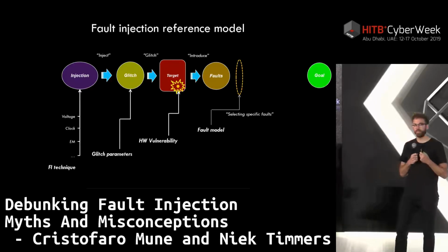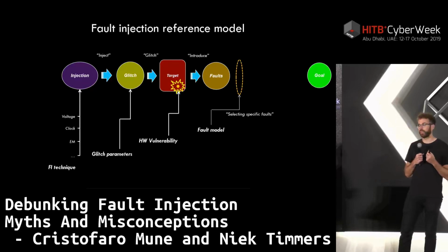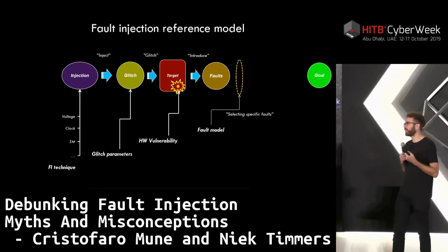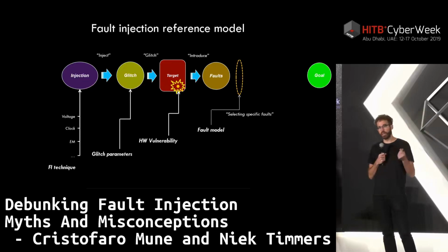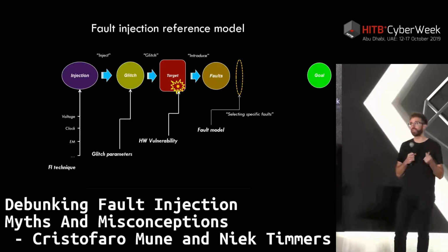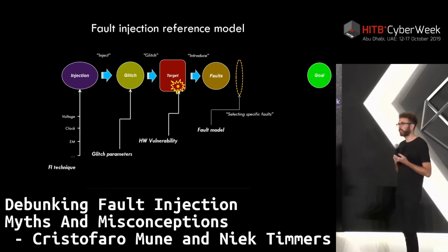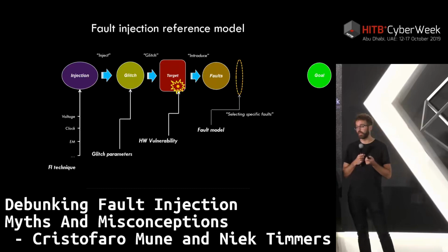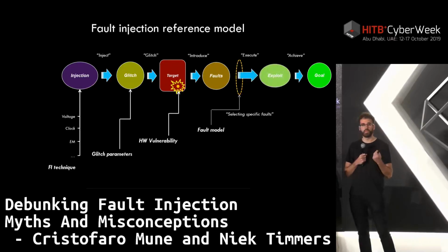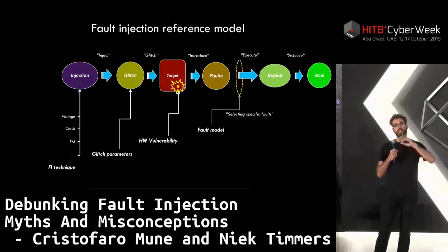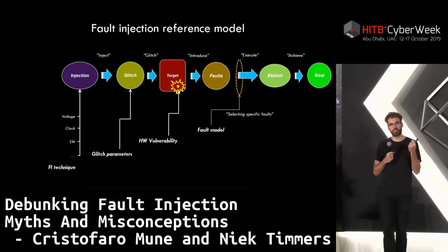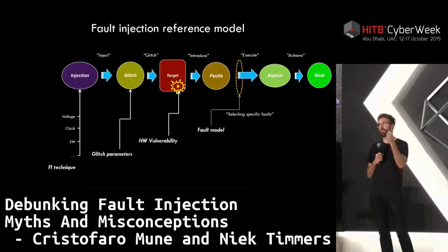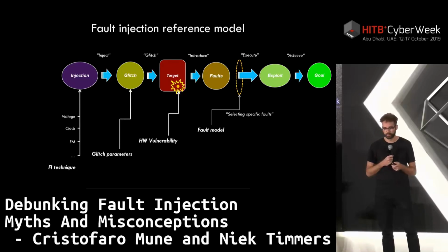The advantage of this is that even though you do not know exactly what faults are happening when you start glitching, you can already make some reasoning about the faults. And if you have sufficient fault models, then you probably cover much of the space of what these faults will do in the chip. An attacker will just assume a specific fault model. For example, I can flip two bits in an instruction, and they use that model in order to mount the attack. So the exploit is actually designed around the fault model. You just assume that you have some primitive in hand, and you can use this primitive to do something. For example, as Christopher showed, we use this to escalate privileges in Linux.